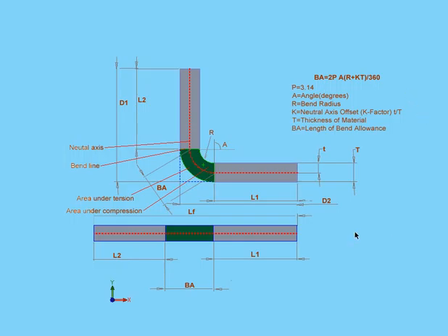The general principle of this formula goes like this. The neutral axes are in my diagram here in red. They don't change during the bending process. During the bending process, the material inside the neutral axis will compress, and the material outside the neutral axis will stretch. The neutral axis will be closer to the inside bend. The inside bend is indicated in blue in my diagram. Now, the more the part bends, the closer the neutral axis will lie to the inside of the part.